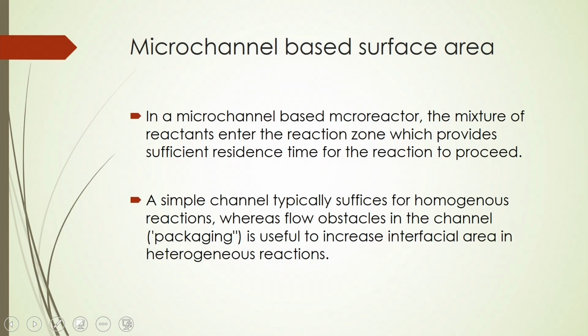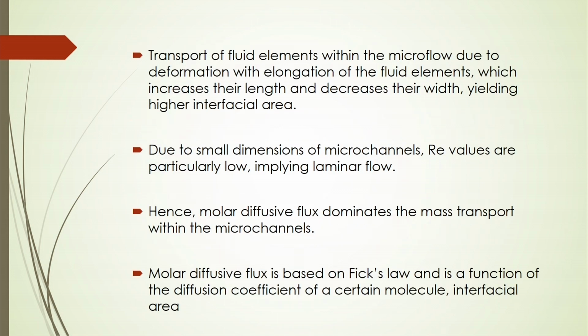In this case a simple channel typically suffices for homogeneous reactions, whereas flow obstacles in the channel, such as packing, are useful to increase the interfacial area in heterogeneous reactions. Transport of the fluid elements within the micro flow causes deformation with elongation of the fluid elements, which increases their length and decreases their width, and that may yield higher interfacial area.